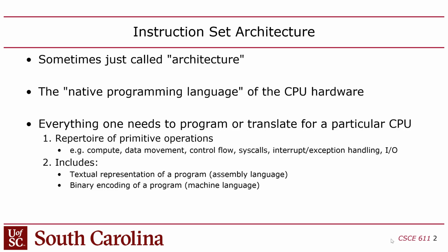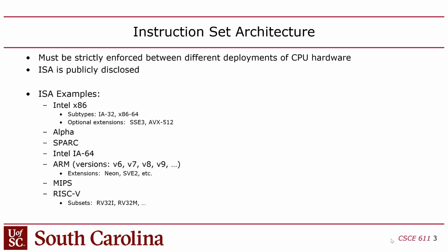So just to give you a quick preview, the program will calculate the square root of an input number. When you have that program running on your CPU, you'll be able to enter the number through the switches. The CPU will calculate the square root through a combination of the assembly code you wrote and the hardware that it's running on, and then it will display the answer on these hex displays. So you'll be basically implementing a calculator from scratch, developing both the hardware and the software for it. So that's kind of the